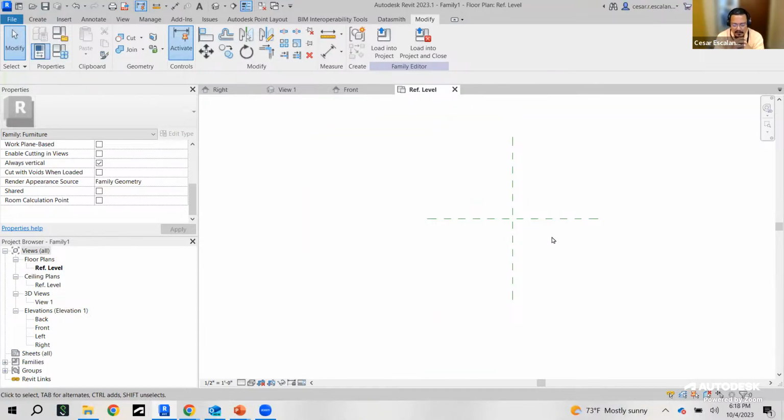All right, so in order to create this representation, I also need to decide what's going to be the insertion point. And when I build this type of family, think about the user. What's the user experience of a family? So if a user is going to be creating rows, or an array, of cabinets, maybe the insertion point of the cabinet should be like that.